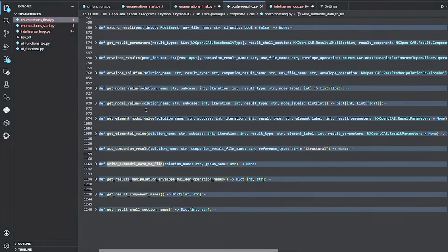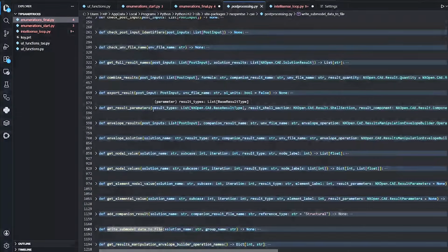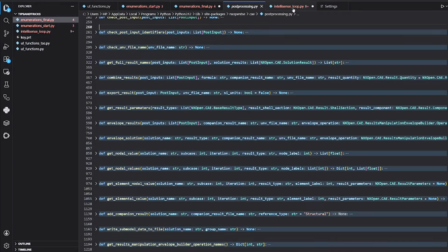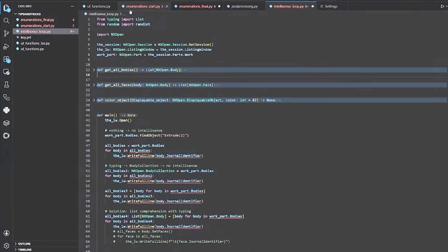So with these functions, depending a bit on what your analysis exactly looks like, you can build an entire structural analysis from mesh. You would still do the meshing by hand, but from then onwards, loads, boundary conditions, solving, and post-processing. Also, I have it somewhere else, I think.